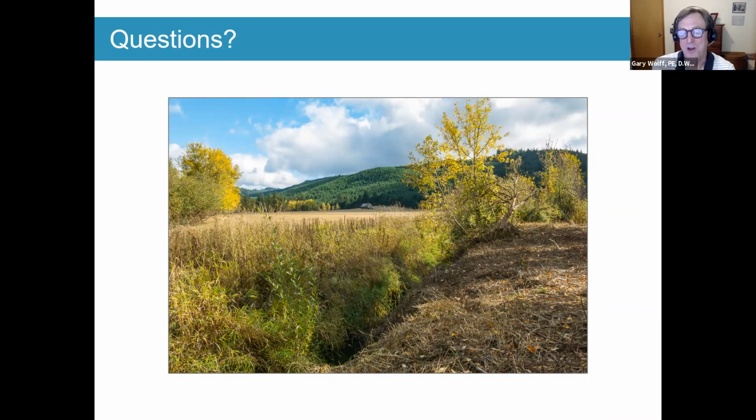I'm actually working on a project in Colorado right now where that's the case. We've got very competent sandstone down below the bridge foundation. Our computed scour depths are below that, but we're saying if you can protect down to that sandstone, it's good. So the next question, so thanks, Gary.